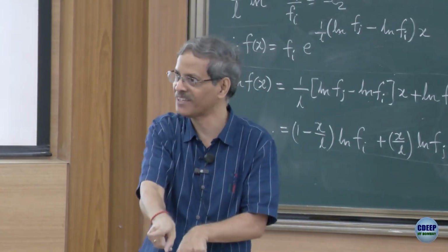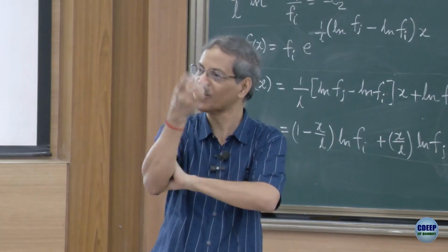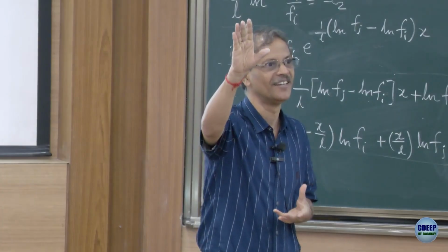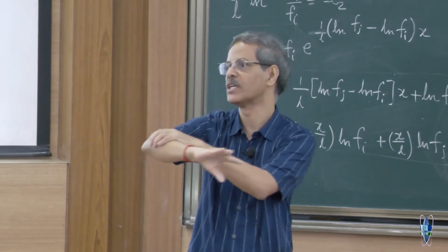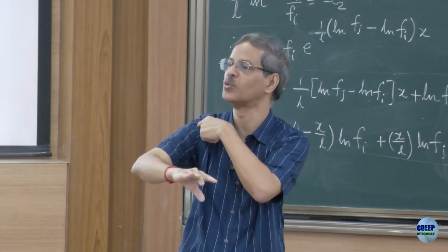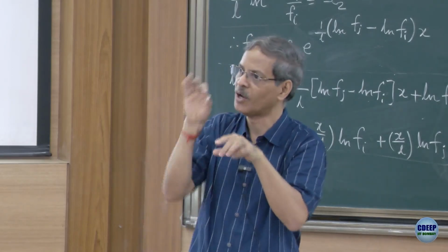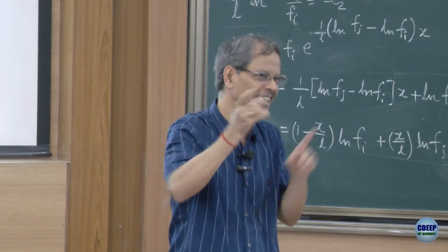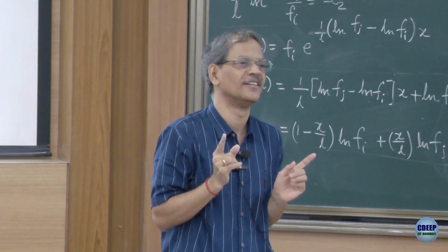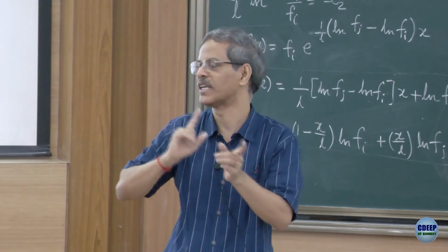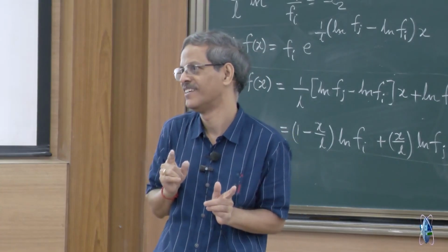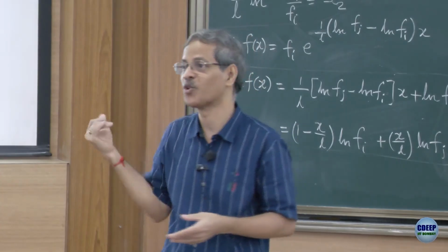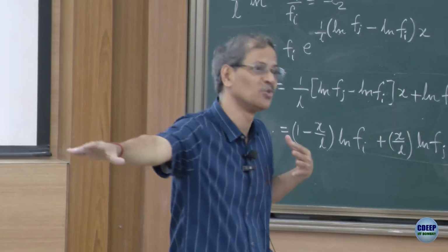XYZ coordinate frame, vis-a-vis the motor only knows its own coordinate frame, it does not know what happens, right. Vis-a-vis what you get at the joints, which you would regulate through your control algorithm, how much voltage current I am supplying to that motor. So, continuously you will be doing this coordinate to coordinate transformation in robotics, and you would have therefore come across determinant of Jacobian related issues, singularity positions,